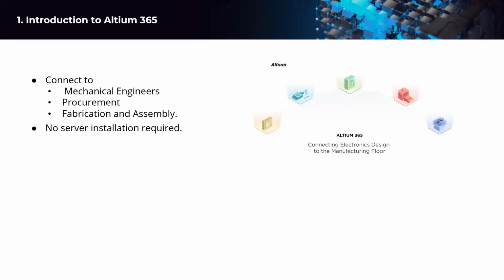When we share your file with the mechanical engineers through MCAD-ECAD collaboration, they can edit your board, like changing the shape of your board, move your components, and make a hole. Whatever changes they make, they can push the board to the electronic department side, the ECAD side, so that you can open it in your Altium software and see it.